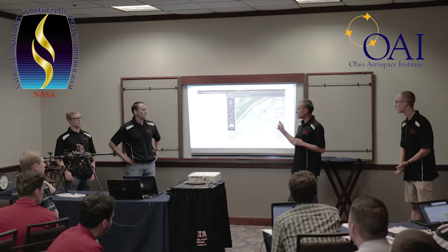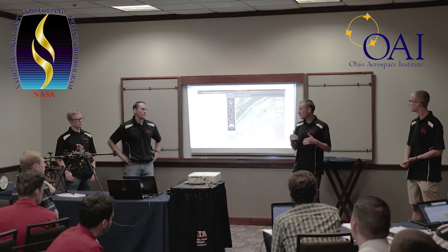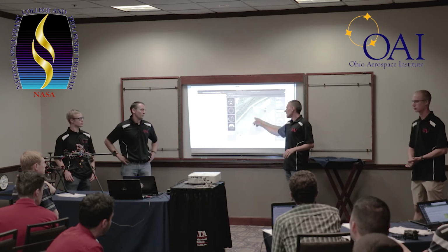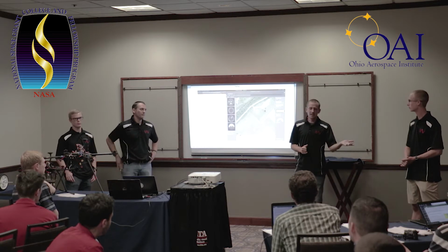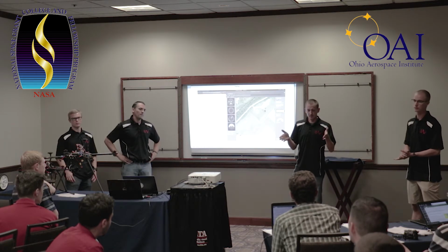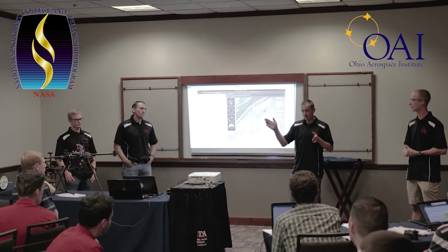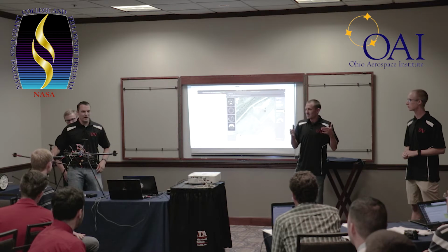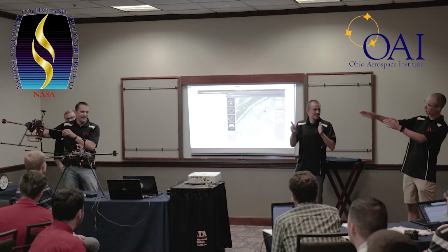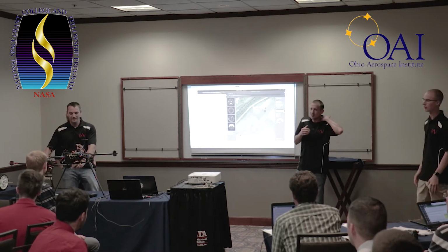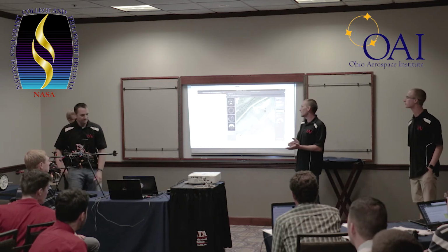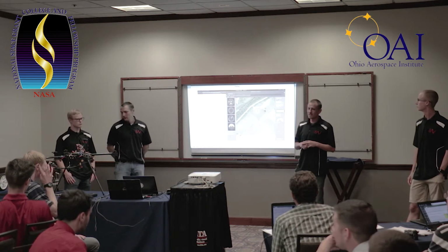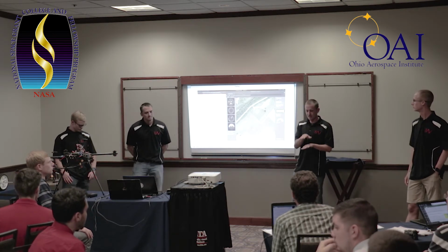And it's easier this way, actually, for safety's sake, for remote pilot takeover, because we're maintaining the exact same heading the whole time as it goes back and forth. So if he has to take over, he knows exactly the way the craft is oriented, which is kind of a difficult thing when you fly these things very far away from your line of sight. Right. So if we can imagine this thing a sixth of a mile away, 200 feet in the air, you might be able to see the landing gear. You don't really know which way it's facing, so knowing the heading is kind of a big thing when it comes to safety. Yeah. So that was also a big consideration in trying to maintain that.